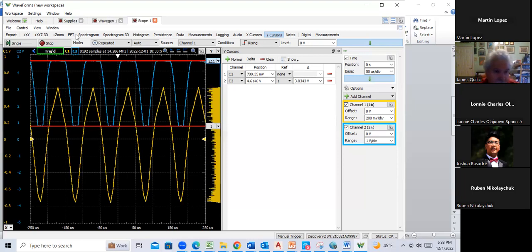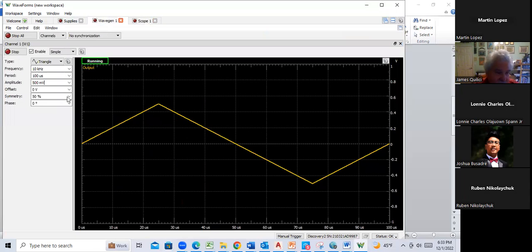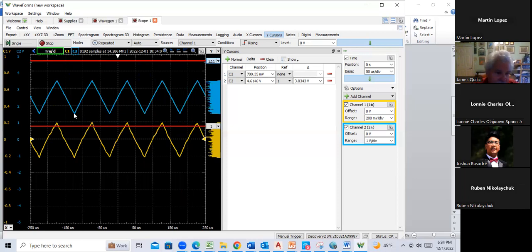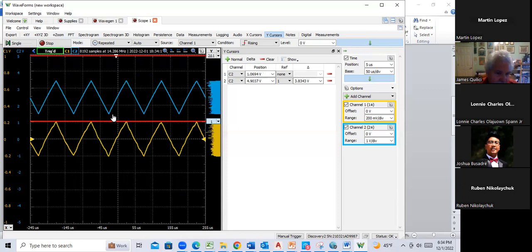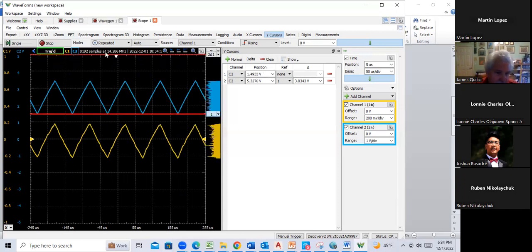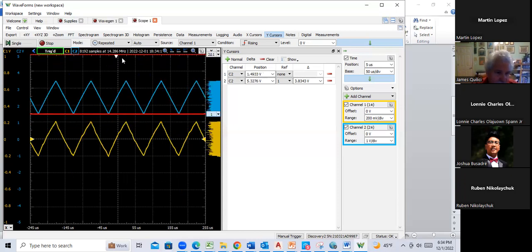And again, look what I'm doing here on WaveGen. I'm not starting with 1 volt amplitude. I started with like 100 millivolts. And so this jitter bugs me. But anyway, I've got a nice clean waveform with 100 millivolts. And this is basically 100 millivolts peak is what it should be.